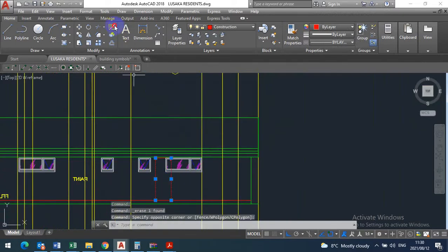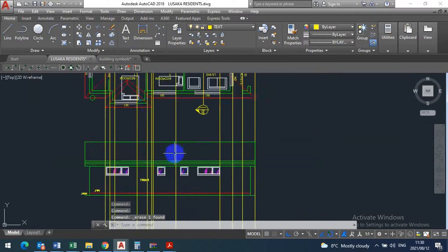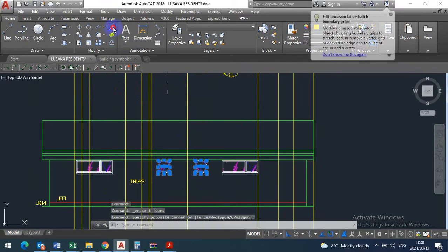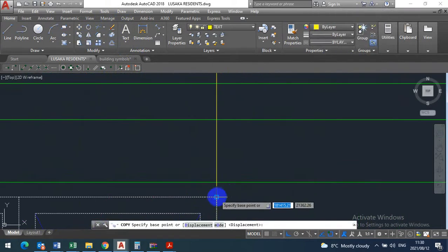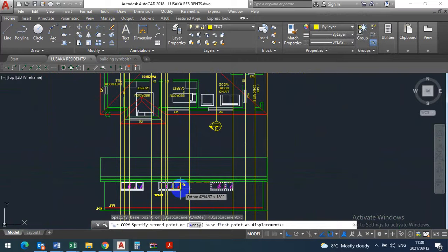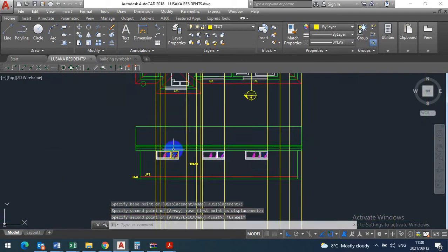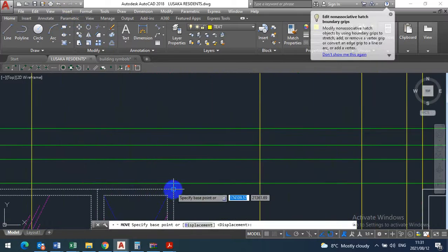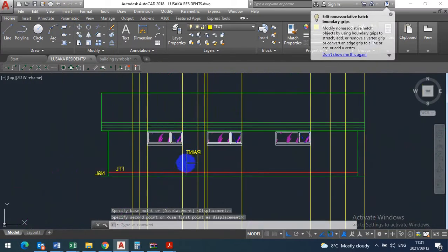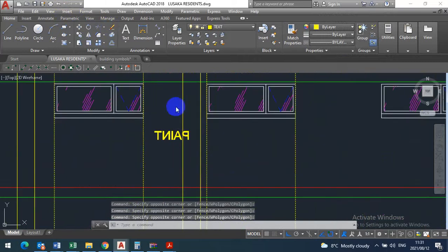There's no door. Delete. This door is on the other side, elevation. Delete. There's no small windows here. Delete these windows. There's another window 1 here, so I'll copy this window again. Window 1. From here you go straight to the next line. Here, another window 1. I'm just gonna move this window. Move there. Delete the lines for windows to remove unnecessary lines. We're done with the windows.